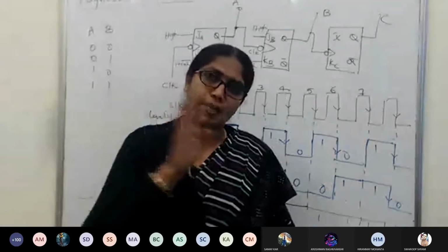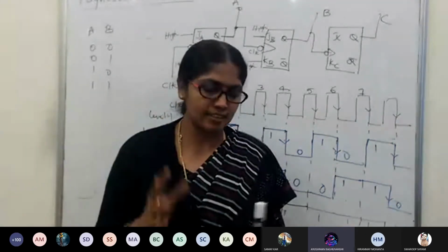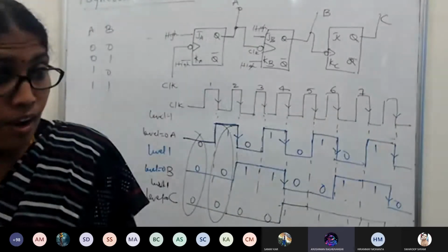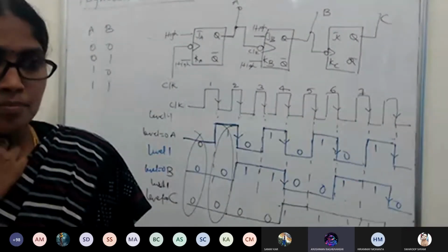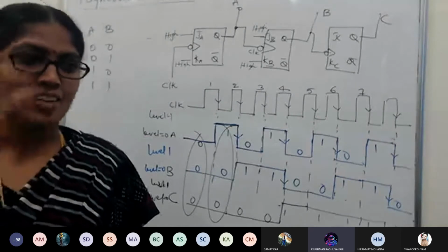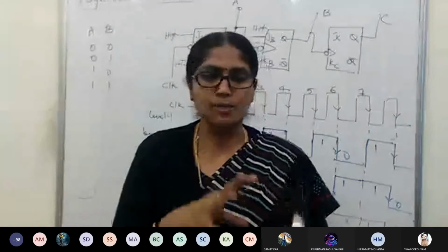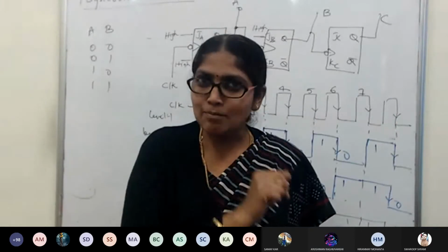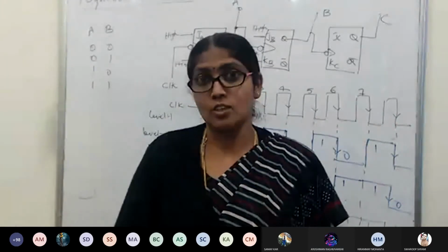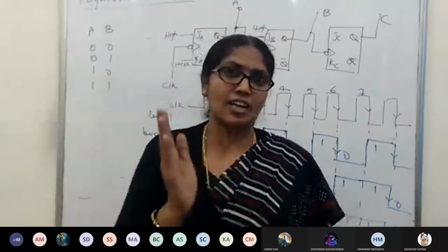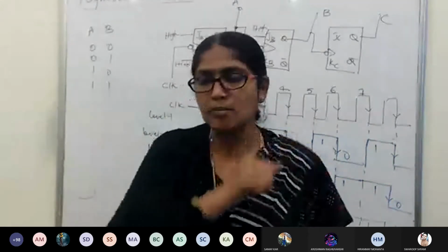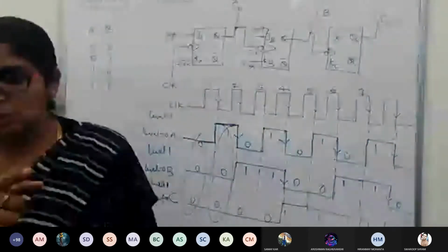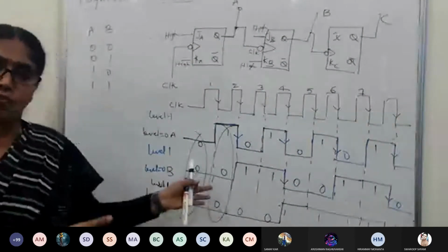We are having a 4-bit counter design. Ma'am, we can pass a low signal in J A, J B and J C using some gates, and whenever there is 10, hold on, connection. So that means you have to do some extra work on the actual design. That means you have to take extra effort so that it will stop and again restart. Don't you think so? That's how the don't cares have come into the picture. When the don't cares have come into the picture, what does it mean? I want only till 10. So 11, 12, 13, 14, 15 are unwanted states.